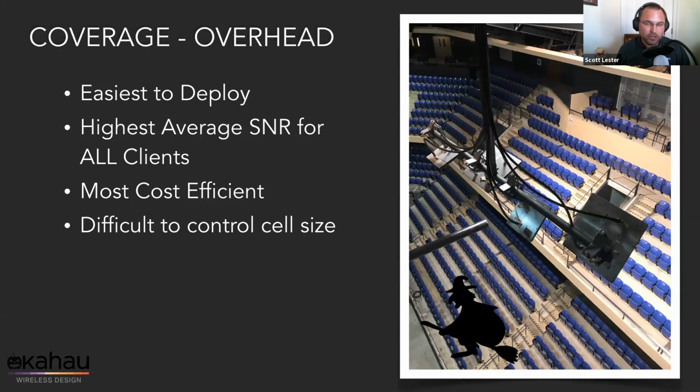If you utilized a 30-degree beam width antenna and you mounted that antenna at 50 foot from the user device, you're going to look at roughly a 58-foot diameter in your cell size. Just rough math. 50 is probably a little close for a lot of different arenas and places that you might be deploying. So let's say we go to 100 feet. Just a 50-foot increase in the distance away from your intended coverage area increases your diameter from 58 feet wide to 116 feet wide.